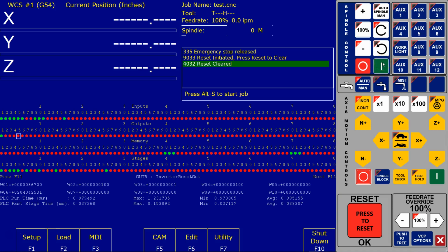Okay. This is also very helpful because a lot of times if you're trying to verify whether something isn't being turned on, or to see if it might be an issue with your wiring, you can easily go in here into the PLC program, force an output on, and verify that the wiring of everything inside the electrical cabinet is working correctly.